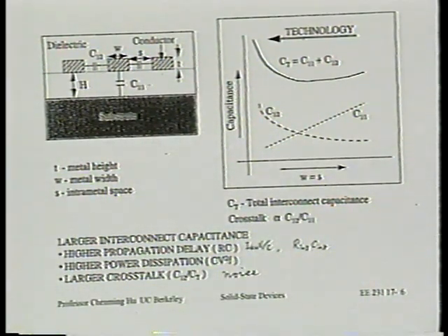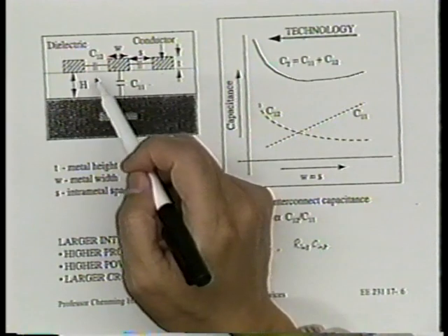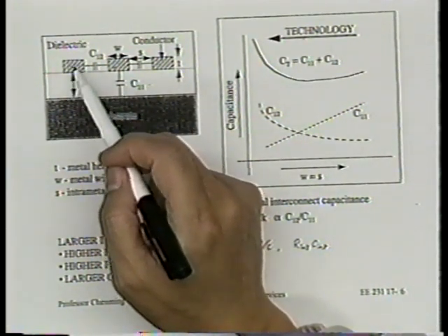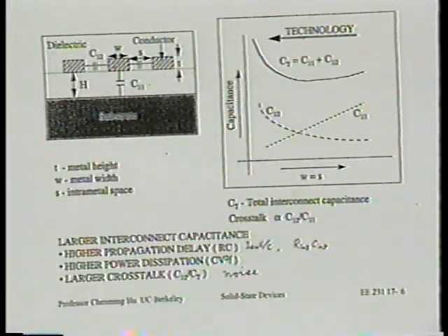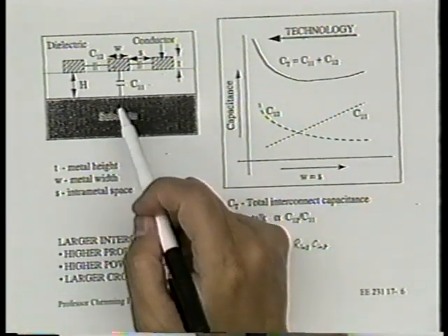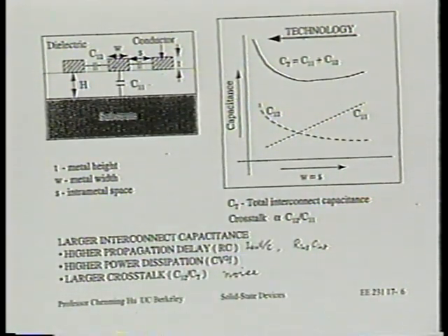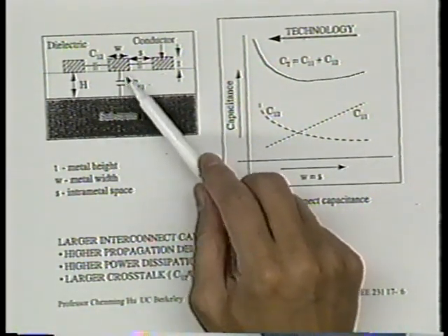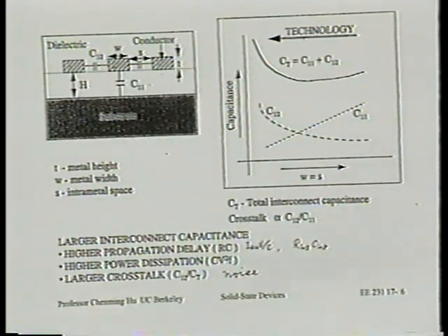All right, it's especially so because the height of the metal is not reduced in proportion because we're concerned about the resistance of the metal line. In contrast, this thickness of intermetal layer, we don't scale this intermetal layer very aggressively. We have been able to allow this metal layer to stay around 1 micron, half micron in thickness.